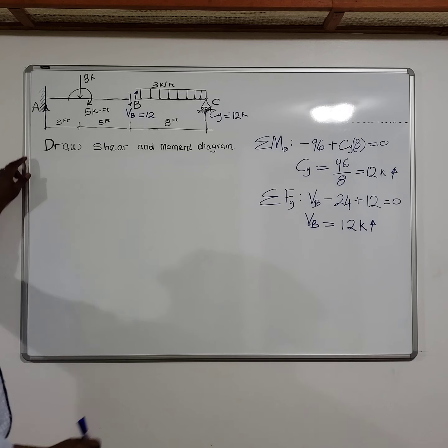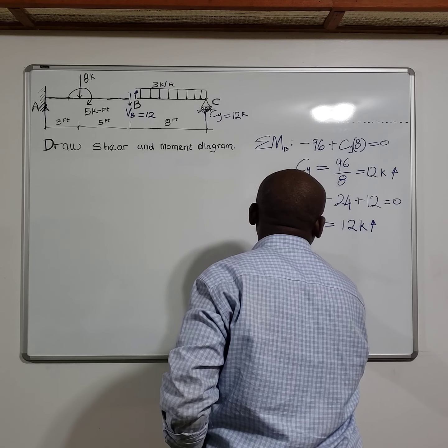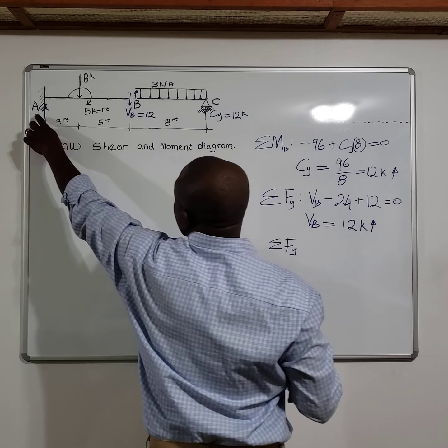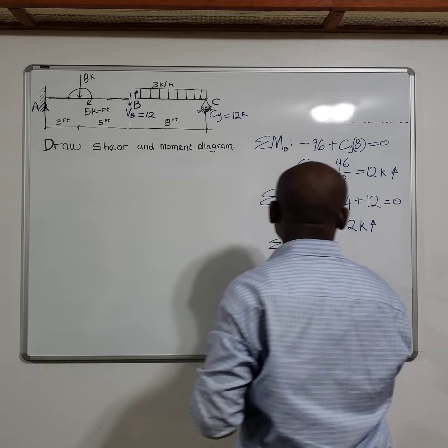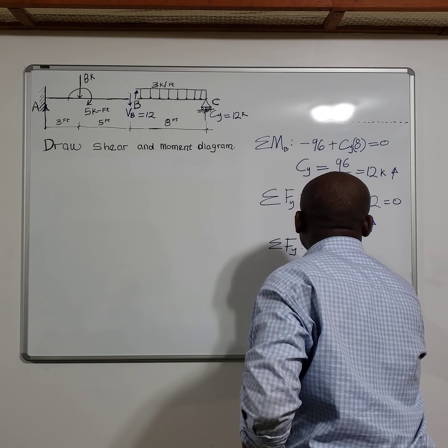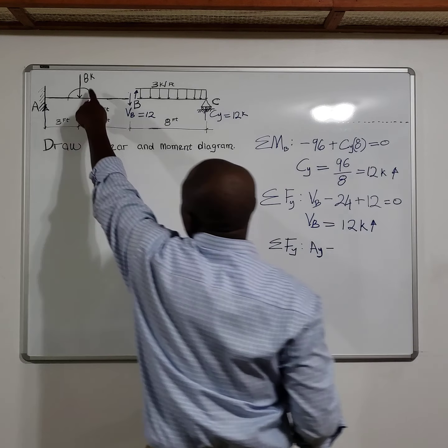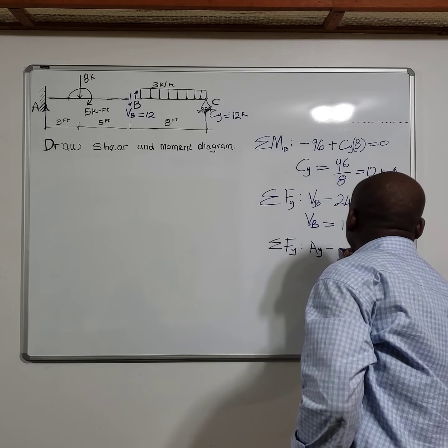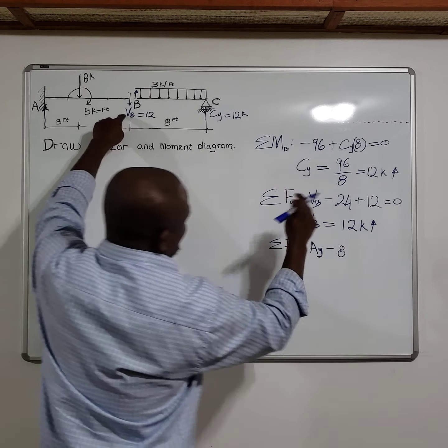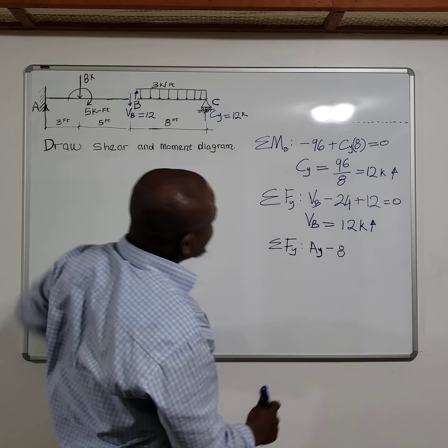All right. So you could do the sum of the forces in Y. We are dealing with this section AB now. The sum of the forces there will be AY. You assume that AY is going up, is positive, minus this point load, 8 kips. Now I said this force, this VB transferred here becomes a negative force, so it's acting downward.